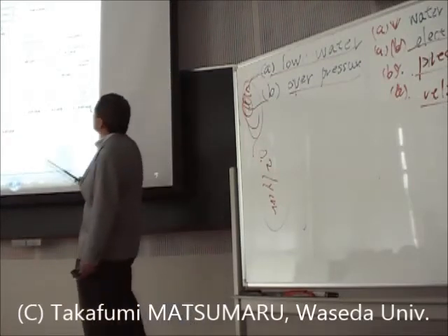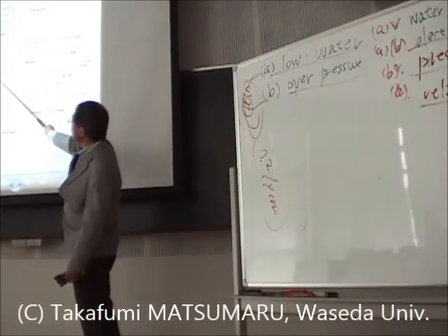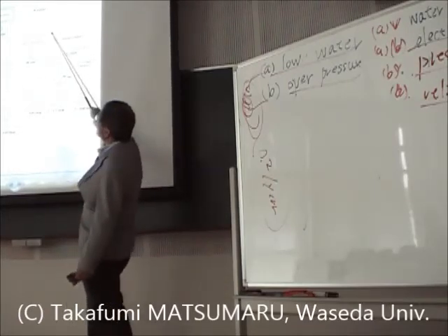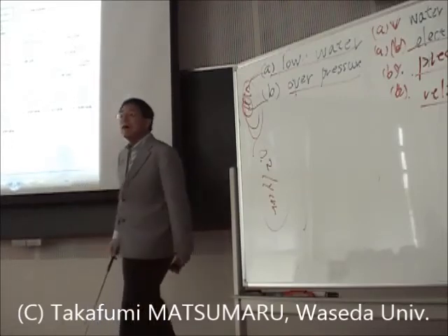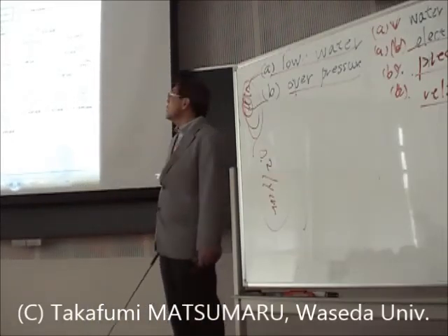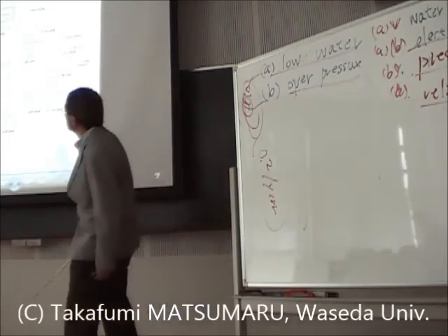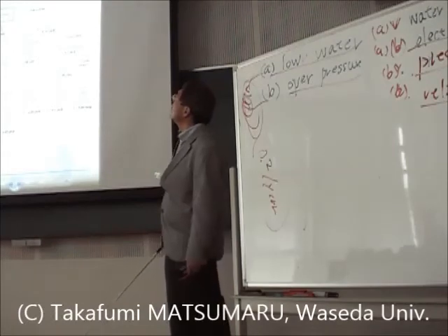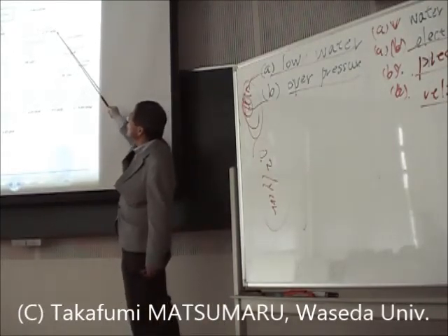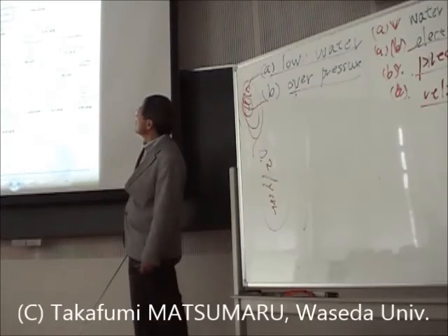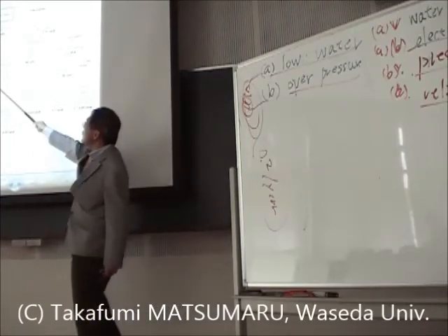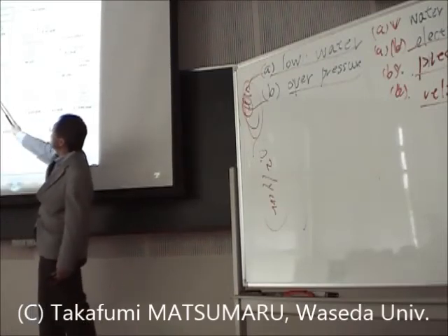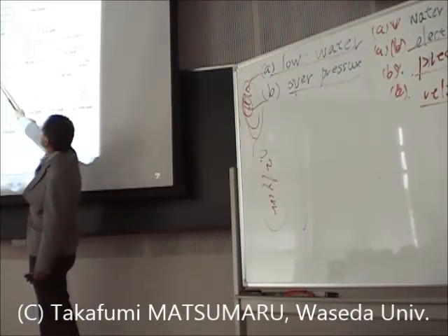Now to get the frequency for the boiler explosion, then again that is the frequency of the low water plus the frequency of the overpressure, and therefore frequency is 0.15 plus 0.2, giving us a frequency of 0.35 per year. So now we have the frequency of the boiler explosion. But from the question we were told that the operator was exposed for 20% of the time. So the frequency for the operator being exposed is equal to 0.2 per year with the 20% of the time.